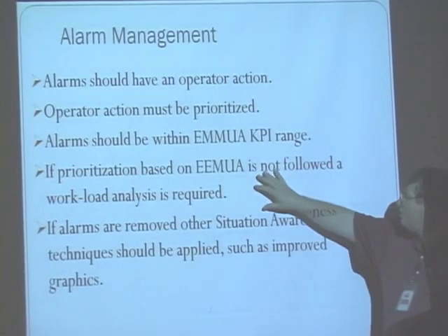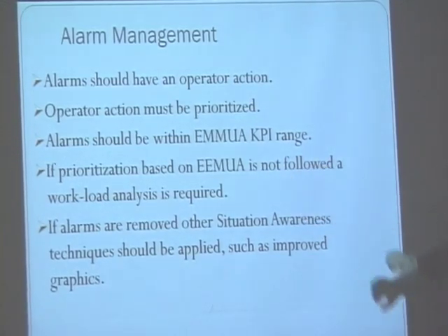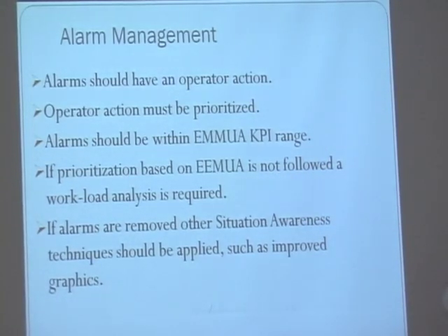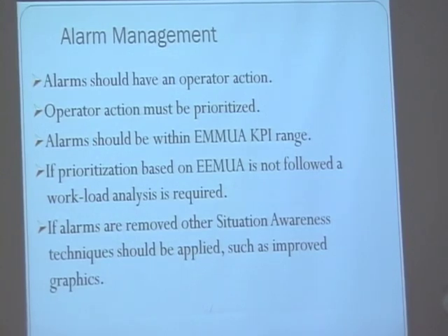If the prioritization based on EEMUA is not followed, you should be doing a workload assessment to figure out how many operators you actually need. Because the chances are you're overwhelming one operator, and one operator cannot cope with that system. If alarms are removed, you've got to do something different, because alarms are a tool in situation awareness.